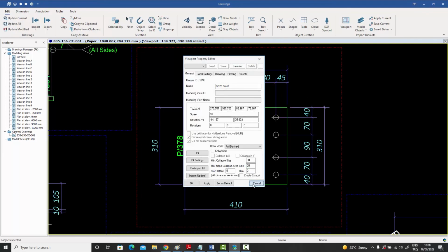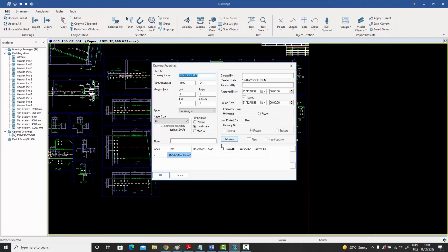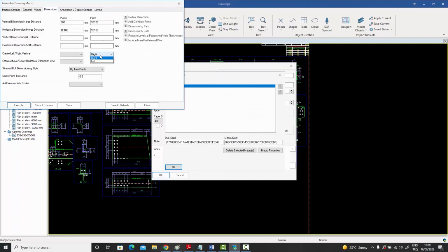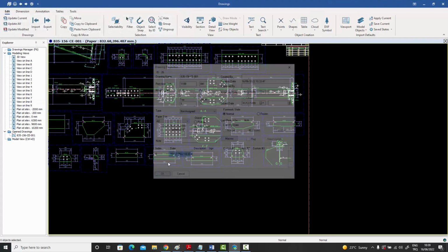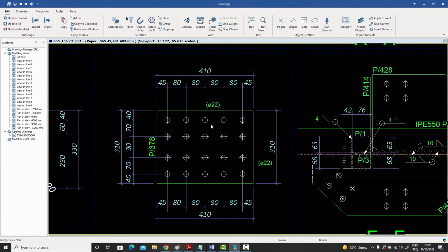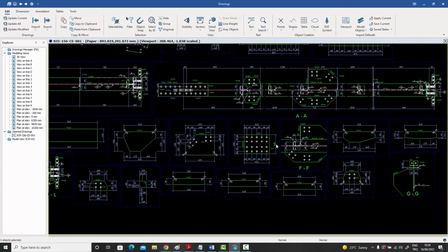For example, if I double click on the macro again, go back to my dimensions and just leave it at default, which was the way it was, and say execute, and I go back into that one again, you can see that it has collected. This is the default behavior. You can have both. The default behavior is that above and below have a certain limit, and left and right have certain limits, so you can go and modify these numbers.